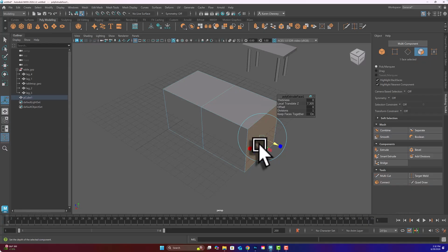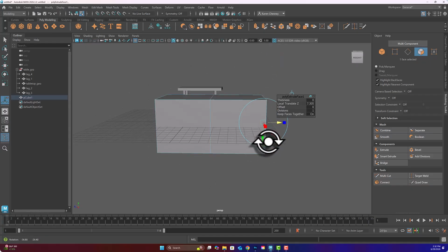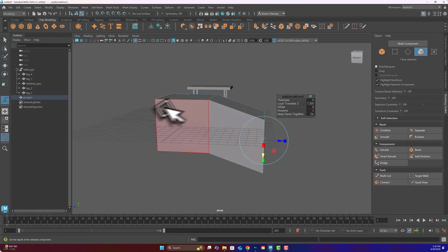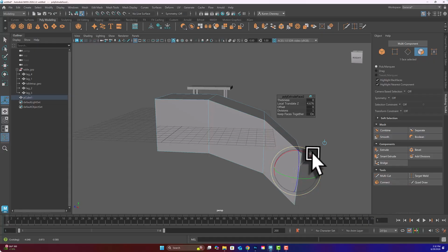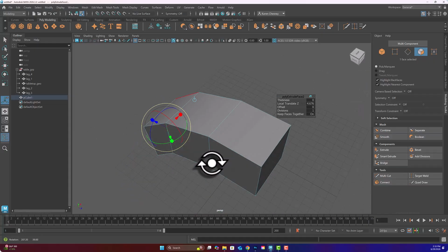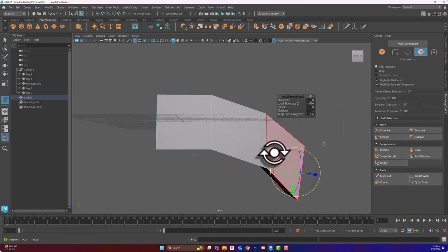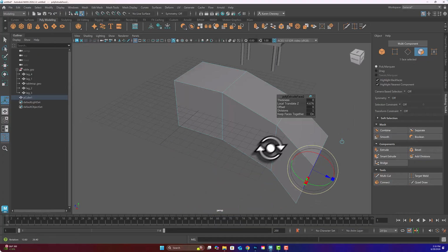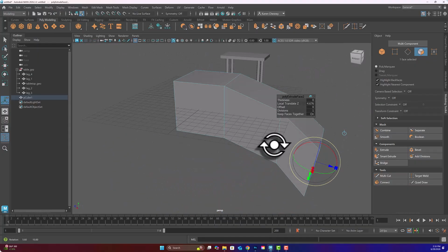Okay, so the reason for this is, let's say I need slightly more division. So I'm going to move this down. Let's say I'm trying to make a curved handle. Then I could do this again. I could extrude again. And yes, I know there are hotkeys and other ways to do it more than once. And I can keep moving this down. Maybe I want to rotate it a little bit. But the key is whenever I extrude, I must change that face. So let's say I'm making the curved handle of an axe or a knife or a pew pew.